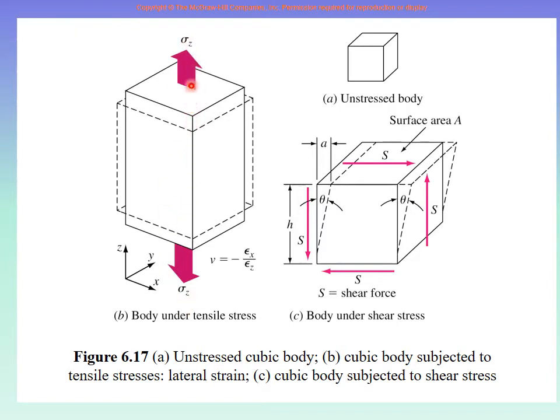So when you apply those loads and it deforms, it changes in length, right? The length increases, but the size on the other side decreases. It was until here, now it has decreased. Here also, the size was until here, it has decreased. So in the x direction and in the y direction, the size has decreased. In the z direction, the size has increased.